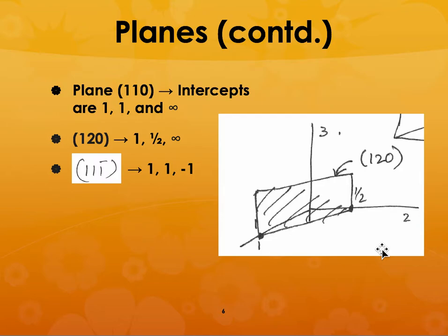Suppose you see something and you can characterize it as a particular plane, and if you see a lot of them, then you know that this is one particular type of material. For example, the close packed direction in face-centered cubic would be something, and the dislocations or the deformation striations are mostly seen in that particular direction or that particular plane. So if you see that, then you know that it is this particular material.